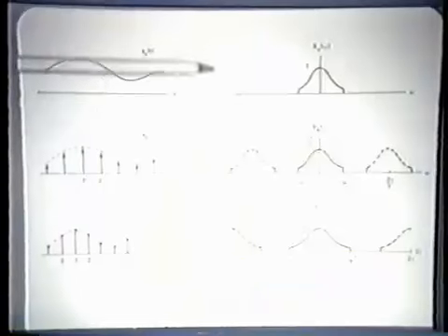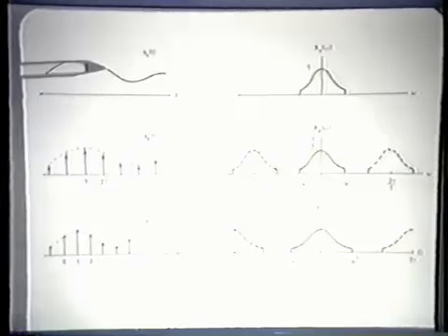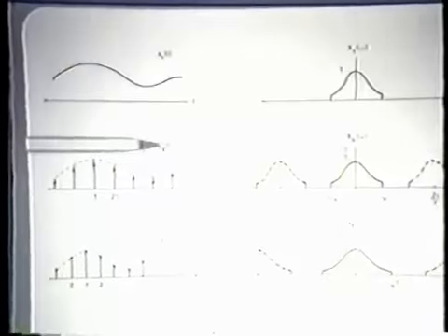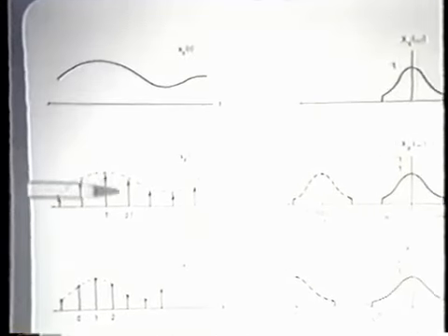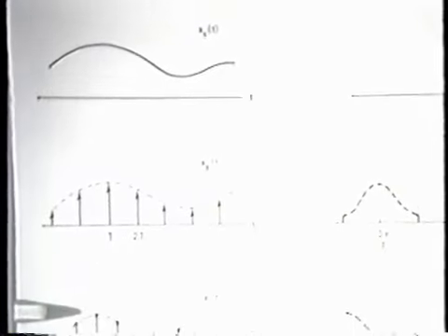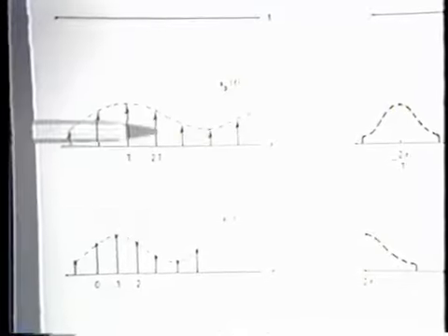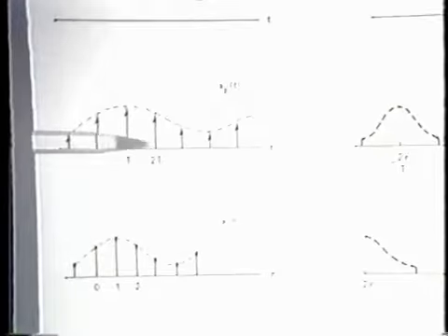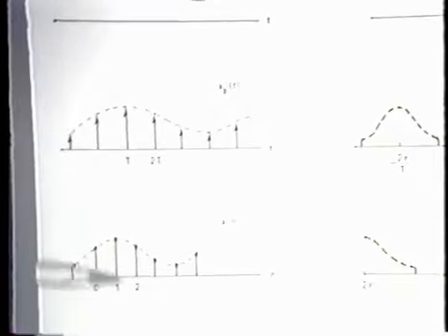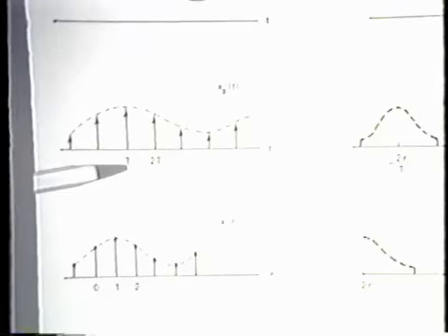And in particular, in the time domain, we begin with the continuous time signal, which is then sampled with an impulse train and converted to a sequence by simply generating a sequence whose values are the areas of the impulses. And I stress the fact that what this corresponds to essentially is a normalization of the time axis, essentially by dividing the time axis by capital T.